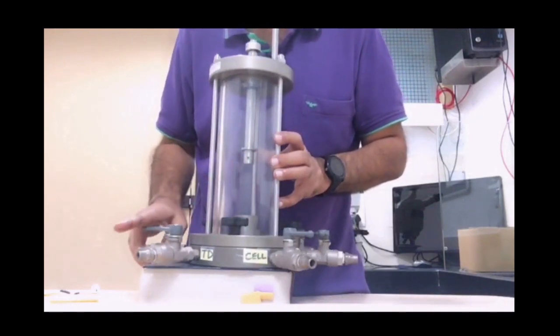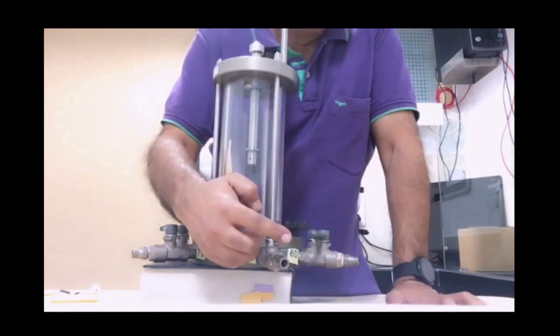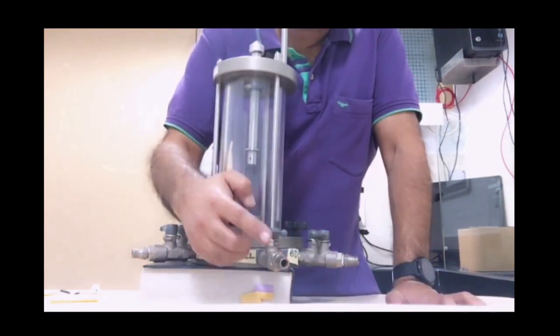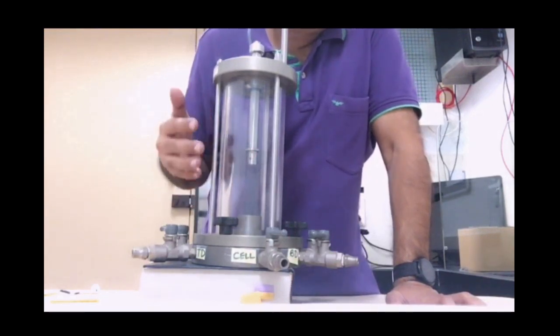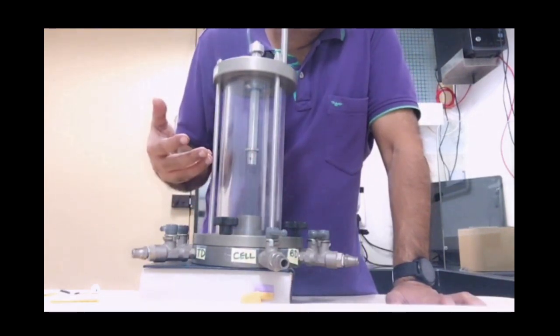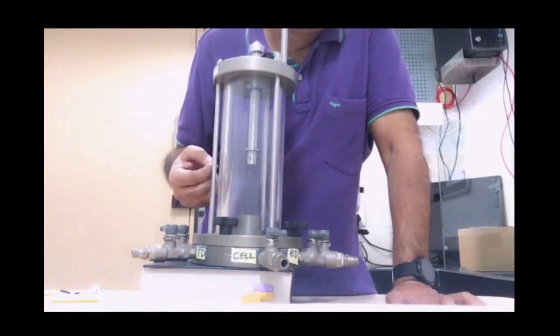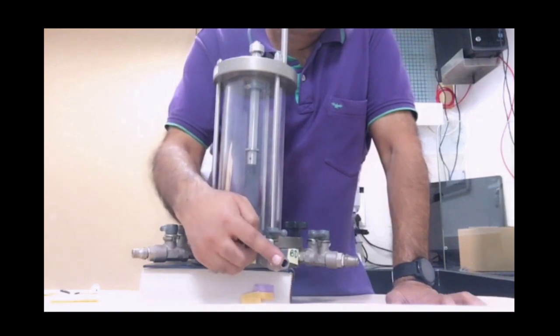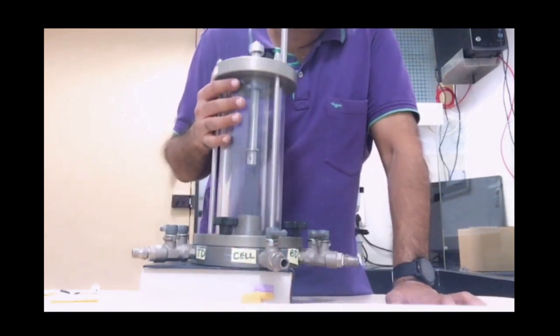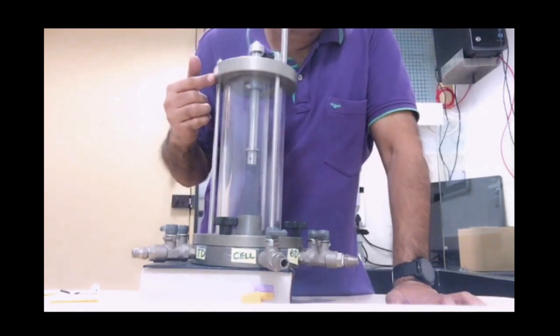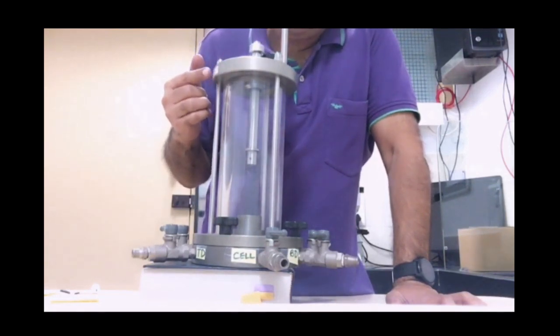I see the pore pressure gauge reading as I increase this cell pressure, knowing that at about 200 kPa or so, the air starts to get dissolved. You would see that in many samples, air bubbles still get trapped here and there, and increasing this cell pressure by a significant amount is not even feasible for the test, because this cell is limited to 1000 kPa working pressure.